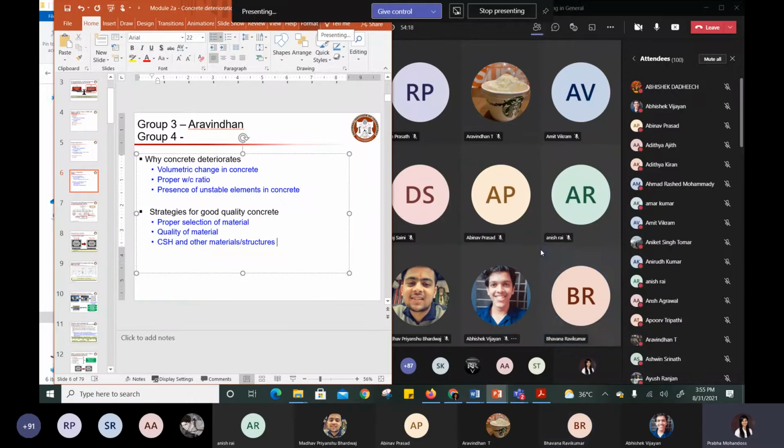the different parts of your concrete, where you may have your hydrated products in the form of CSH and calcium hydroxide, which are very weak components in your concrete, and that could react with chemicals and result in different deterioration. Similarly, when you have reinforced bars embedded inside it, the rebars could corrode, and that will lead to other mechanisms.